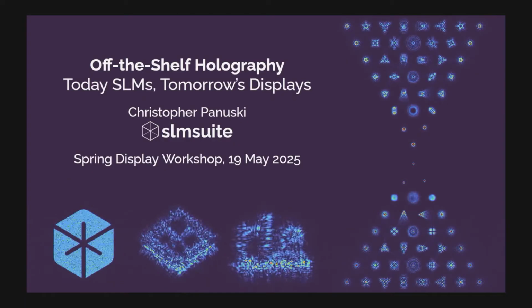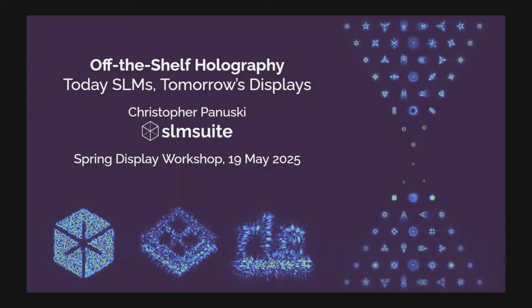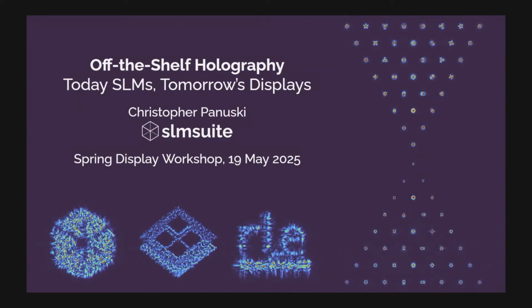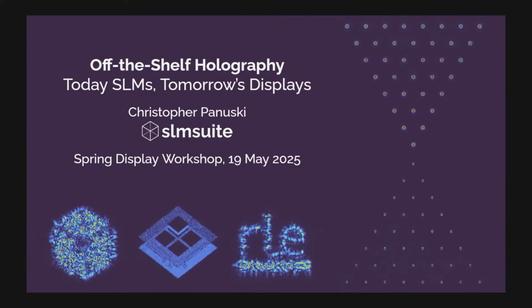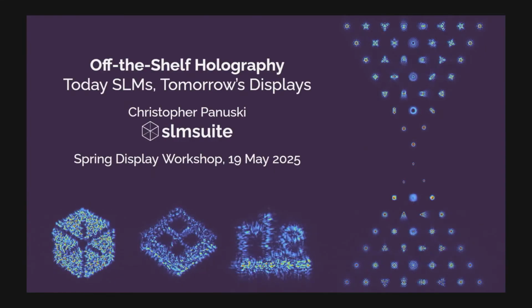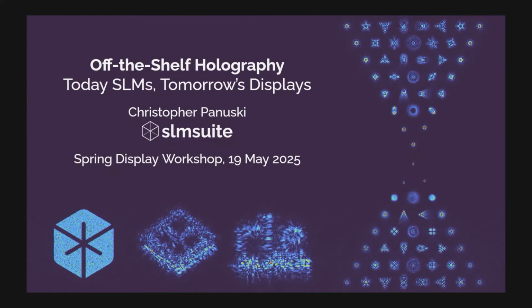So that's the reason why I think that the majority of industry has stuck to amplitude-based modulation techniques like digital micromirror displays. But with the software package that we've developed and are continuing to develop, you can generate images like we've shown in the slide here. So specifically, this entire slide minus the text is generated with a single spatial light modulator pattern. And so what that means is we have to calculate what the pattern actually is to produce the images on the left-hand side. These are sweeping through various focal planes. So you can see that some of the images are in focus, other ones are out of focus, and we're sweeping through the focus for a three-dimensional display.